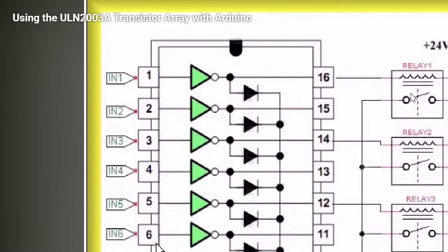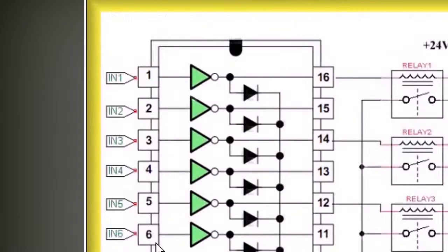So the coil has the property that it can also push the current in the reverse direction. That is not allowed, because microcontrollers have a low sink current. Even in the reverse direction, a microcontroller can accept only 20 milliamps. That is the maximum.